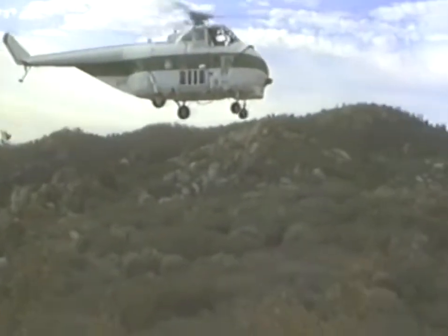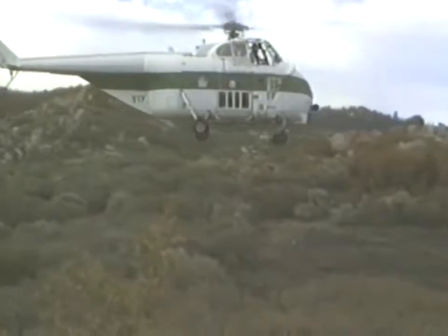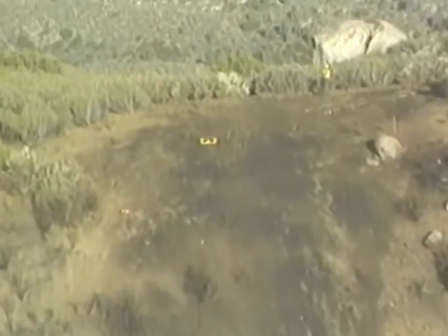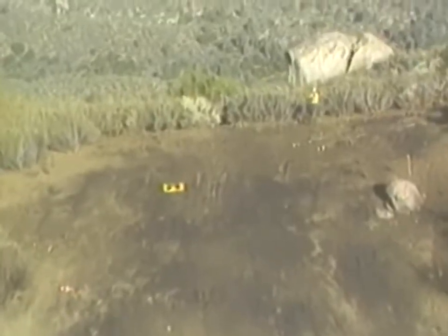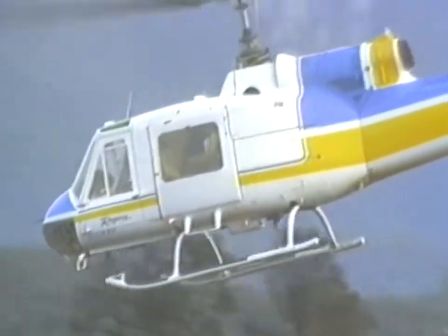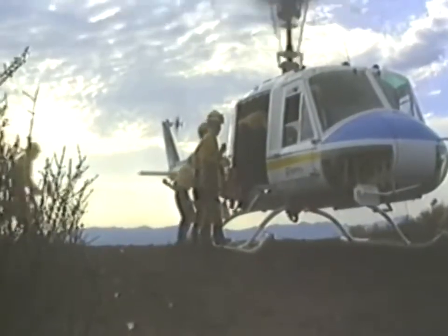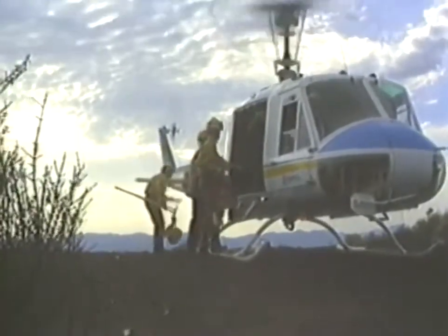As you can see, the helicopter is much more efficient when you can use in-ground effect sites for your takeoffs and landings. And if you must use an out-of-ground effect site, the number of people or pounds of cargo you want to carry may have to be reduced drastically.